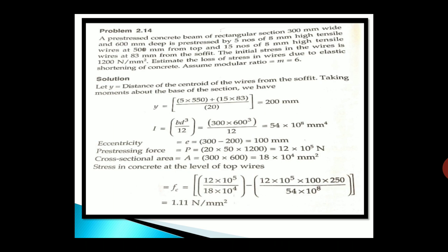So firstly we have to locate the CG of the steel, that is the CG of the reinforcement. As here we don't have reinforcement at a single point or in a single region, we need to first find a common distance with respect to the bottom where we'll assume that all the prestressing forces are acting. That is what we call locating the centroid of the steel.